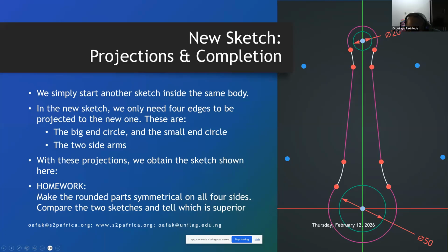Here you have this one. The other one is at the end here. What you need to do is to make sure, if you want to ensure symmetry, you can make these 2 points symmetrical along this line. Once you make them symmetrical along this line, they are symmetrical, and because this is still not green, you can move this and you can change the shape of this line by moving this or this. And the same thing will happen below here.